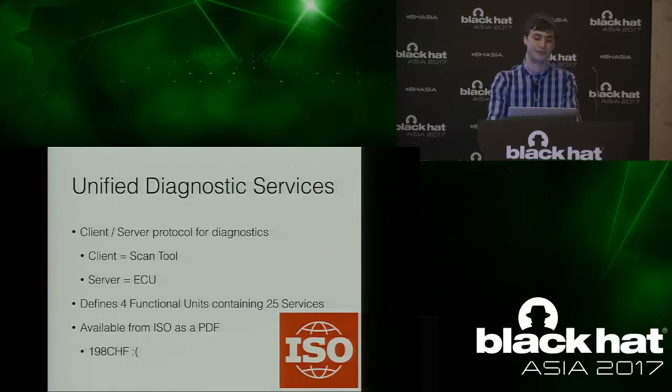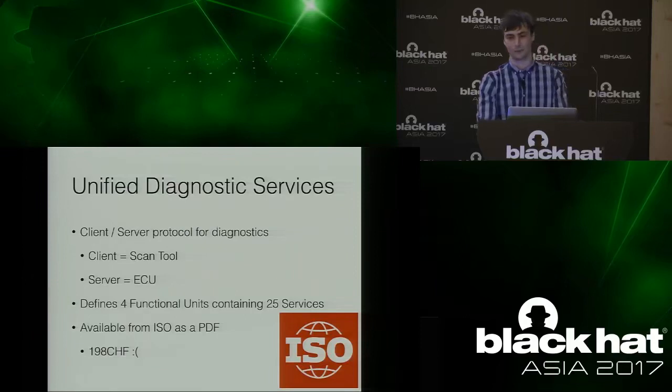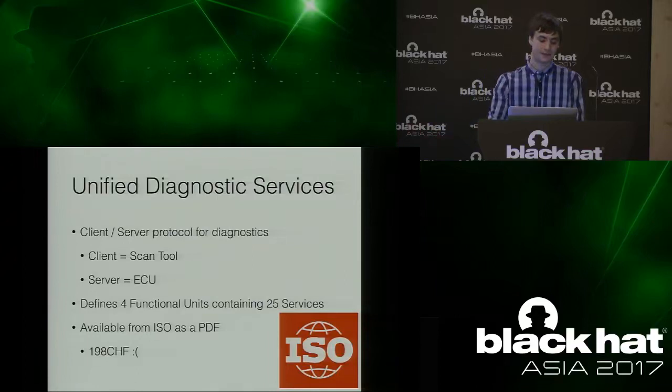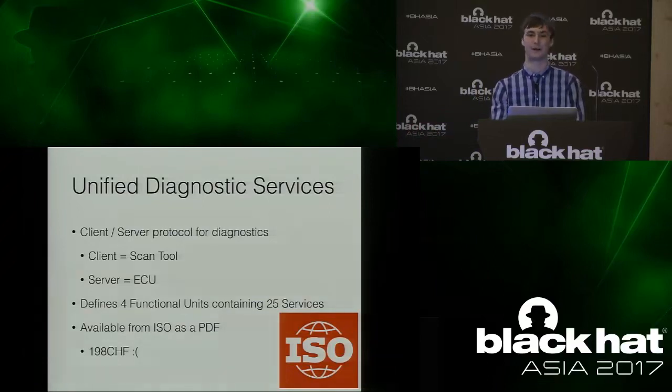Unified Diagnostic Services, which is also called UDS. This is the client-server protocol that's used for diagnostics in basically all cars today. The client in this case is a scan tool, by which I mean the thing you are plugging into the OBD port. And the server in this case is the ECU, which is the actual controller in the vehicle. It defines 4 functional units containing a total of 25 services, and we will go through them and just highlight the fun ones.